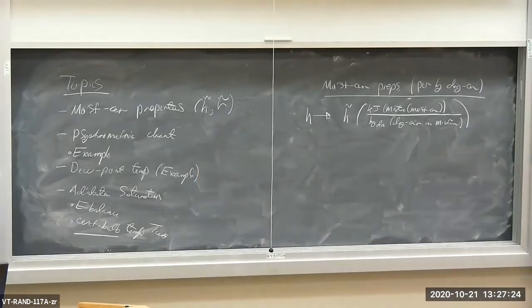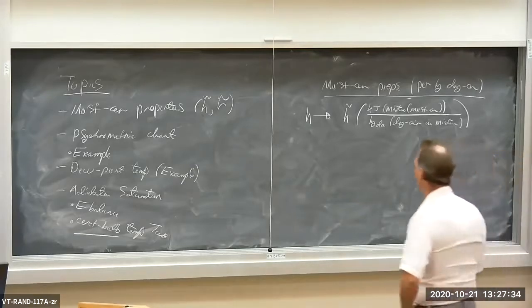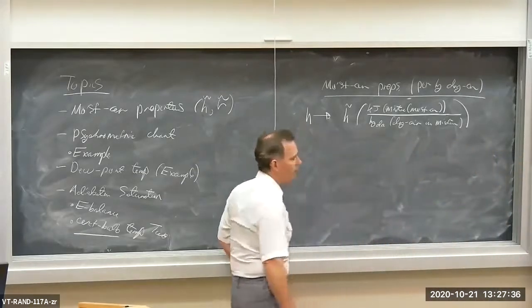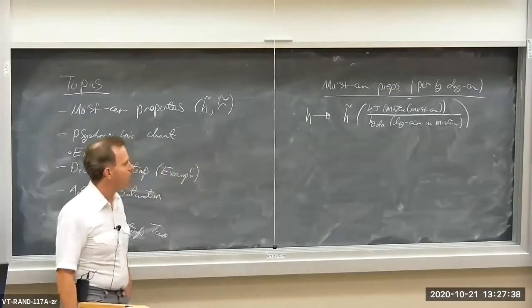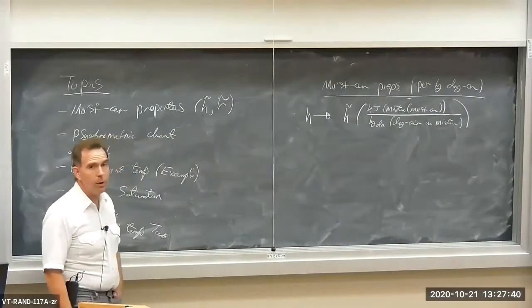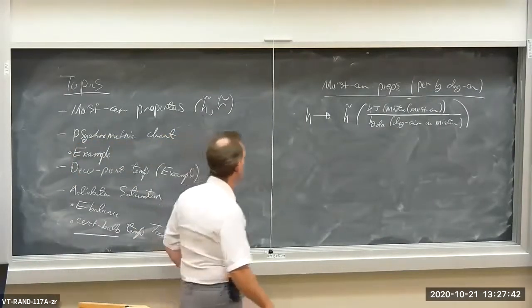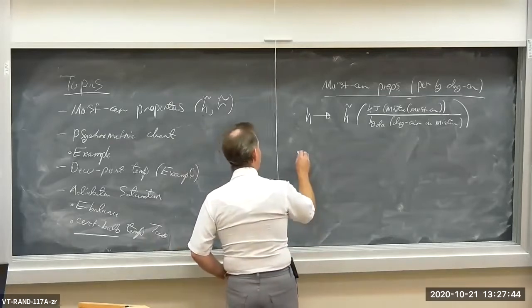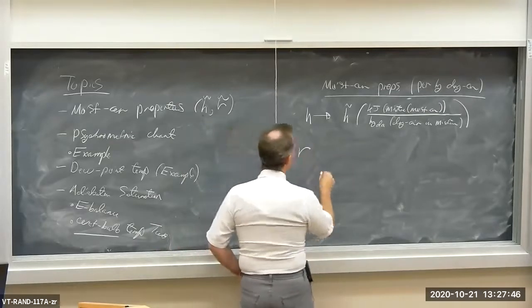All we need to do is figure out what the mass flow rate of dry air through a duct is, and we can calculate the flow of enthalpy through the duct. So expressing moist air quantities in terms of tilde quantities per kilogram of dry air is actually going to be very useful. We do the same thing with specific volume.